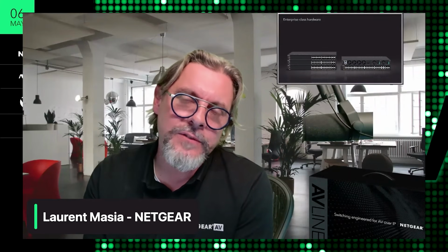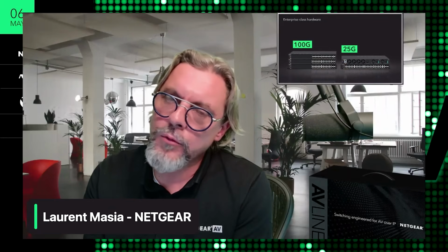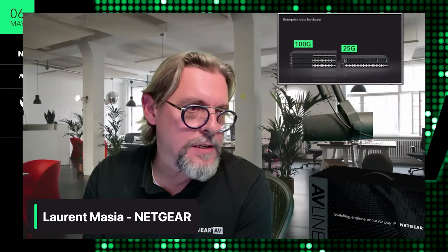Last question I'll take from Kristaps before going to the other. How long are all the cables? So I am assuming that for SDVoE, because we are using 10 gigabit Ethernet, you can go 100 meters on Cat6a, and as far as you want using fiber, multi-mode, single mode, you can even cross the ocean.